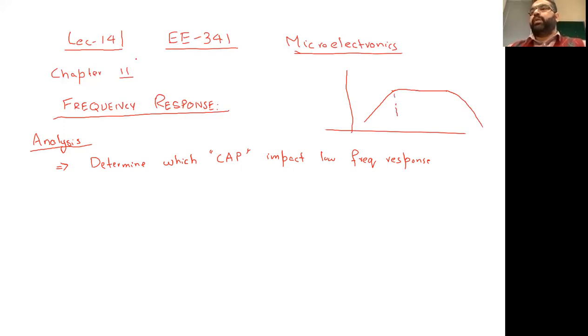So for low frequency we mentioned omega L, for high frequency omega H, and the mid-band gain was the area which we normally use to calculate the gain of an amplifier. We were all the time using the mid-band gain. That DC gain which we were finding was ultimately the mid-band gain, V out by V in.